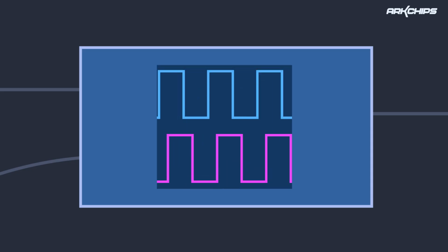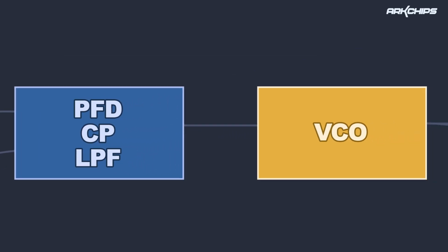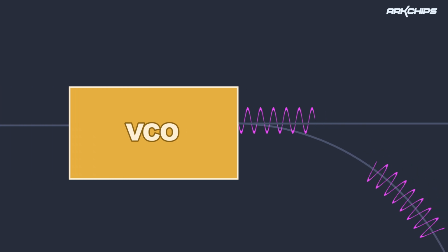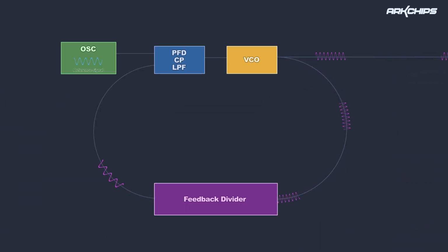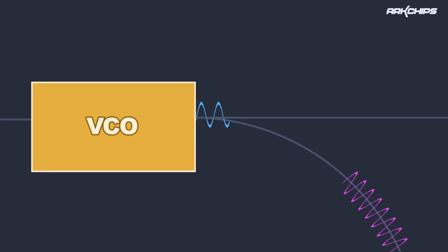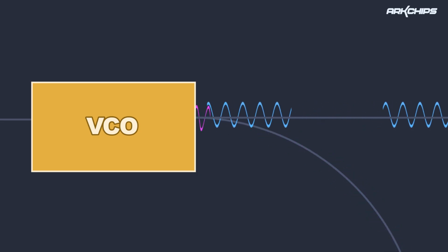The low frequency converted by the feedback divider reaches the stage of comparing with the reference frequency and generating a pulse, which represents the difference of those two frequencies, and converting the pulse into control voltage. This control voltage generates the high frequency in the VCO. After this circular loop cycle, the highly accurate frequency is distributed throughout the semiconductor system and used for high-speed data communication.